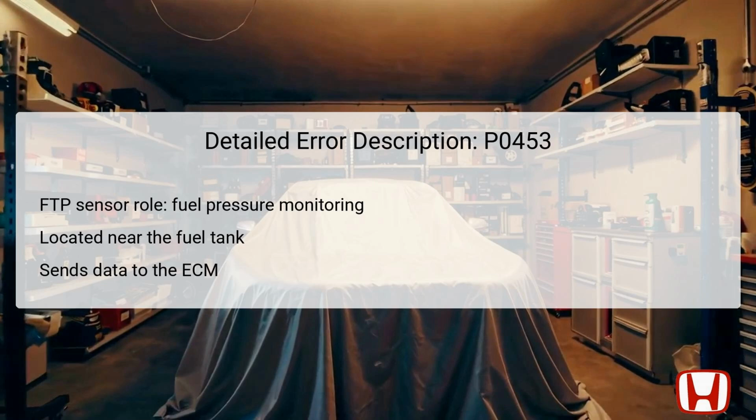The FTP sensor operates by changing its voltage output based on the pressure sensed in the fuel tank. Typically, a voltage reading of approximately 4.7 volts or more signifies a high-pressure state, which could indicate a fault within the sensor circuit and is the basis for the triggering of DTC P0453. Understanding the exact location and role of the FTP sensor is crucial for diagnosing potential faults in the emission system and for ensuring optimal vehicle performance.